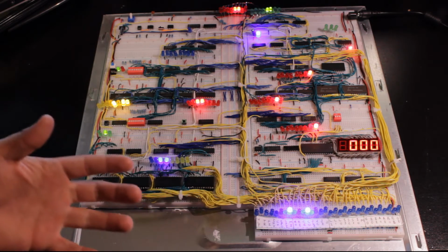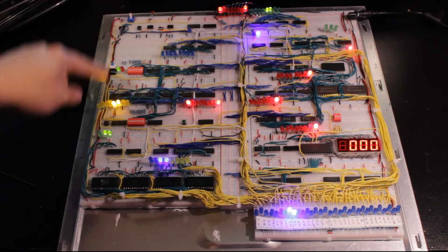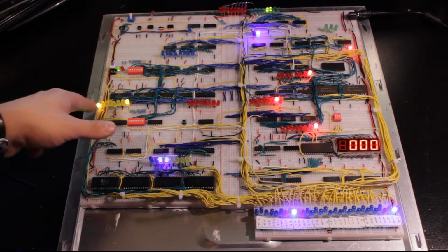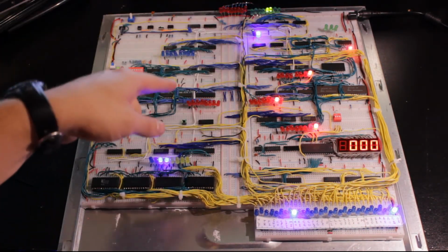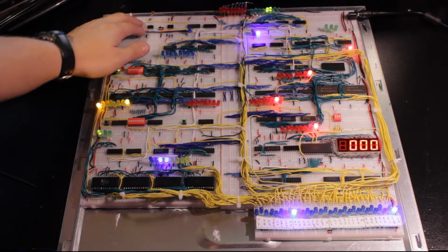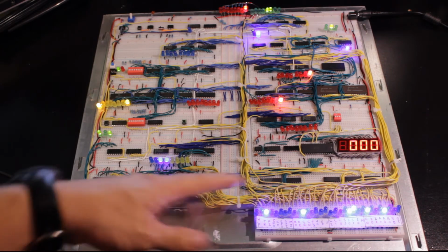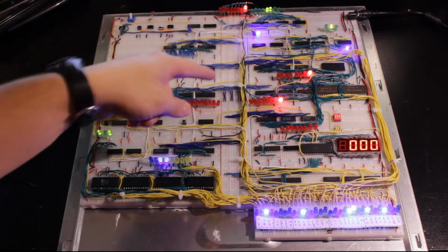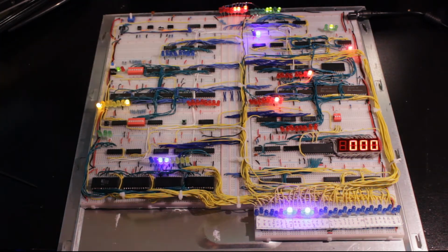Then this is subtraction by pointer, so it's going to get the next memory address byte, 0x81. Take that, put it in the memory address register. Now we take that value 0. It's going to go to the B register, get subtracted from A, and get put into the A register. So watch that 0 go there. We're doing a subtraction operation with lots of fancy blue lights. And 1 minus 0 is 1. We see that result there and on the bus, and it's going to go in A now.